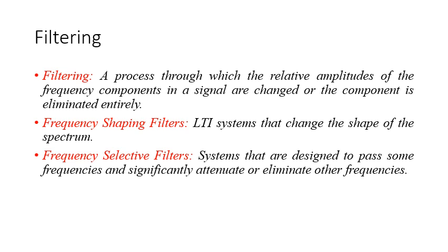That is, if the input is a complex exponential, then the output is H of s times the complex exponential, and we call H of s the frequency response when s has a real component equal to 0, so that is H of j omega, and we call it the frequency response of the LTI system.